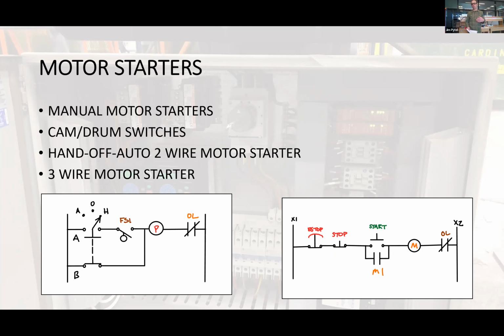So another important concept to understand is troubleshooting. What if this overload was not in an automatic reset, but was a manual reset? Say the motor has gone into an overload, and this normally closed overload contact opens up and stops the motor, and it's cooled, but it hasn't reset because it requires manual intervention, a technician to come along and press that reset. So getting them early in this course to understand, number 1, safety, the difference between an auto and a manual, and number 2, troubleshooting, the difference between an auto and manual. The circuit may be functional, however that normally closed overload is open.